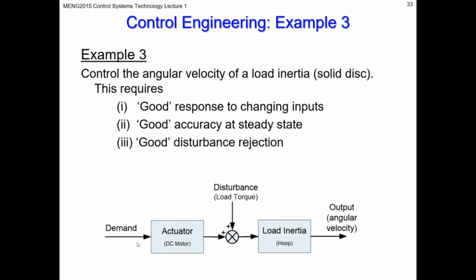Remember, behind a block is just a set of equations that describes the behavior of a particular part of the system. So we can break the system down into parts, and each part could be represented as a block. Any block has an input on the left usually, and an output on the other side, and the input is manipulated by whatever the transfer function or equation is within the block to create the output.